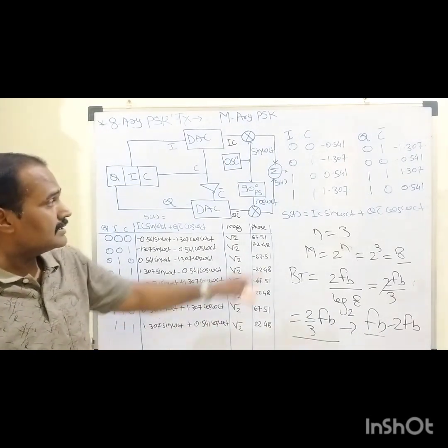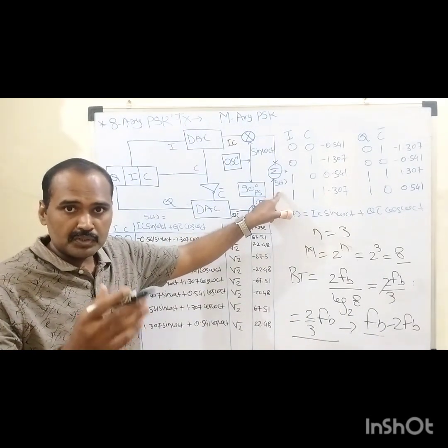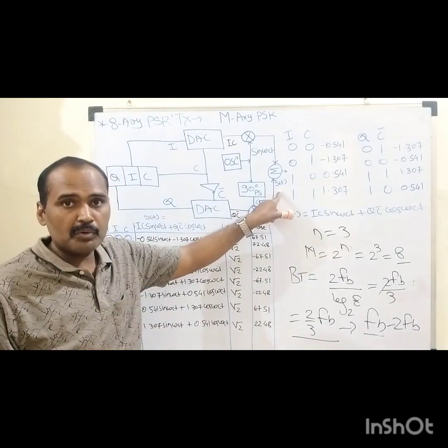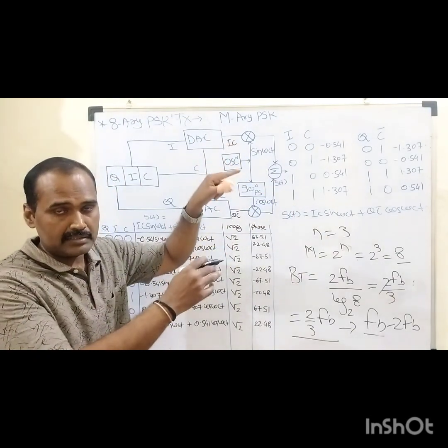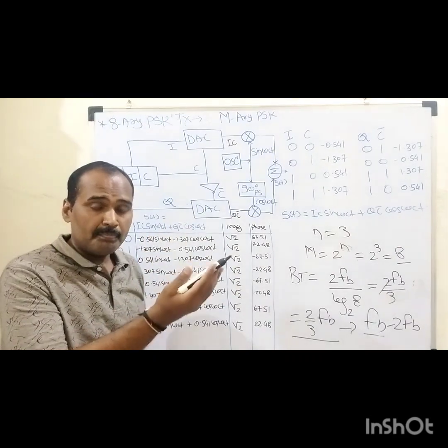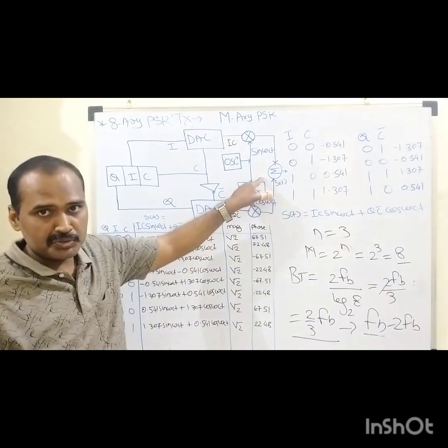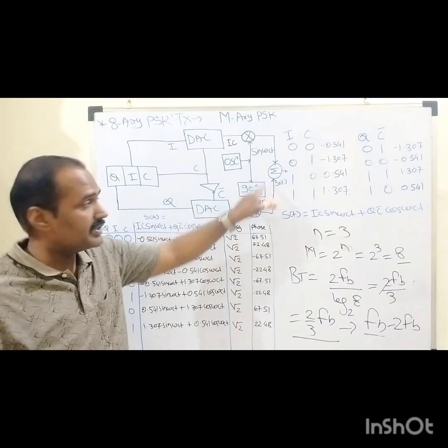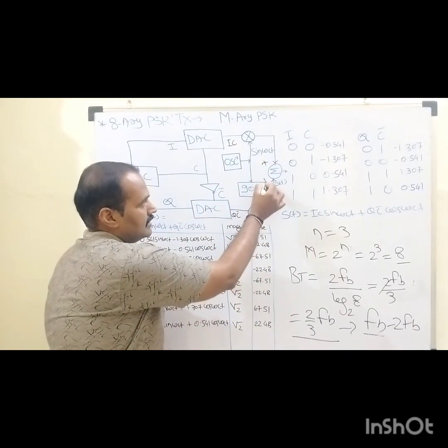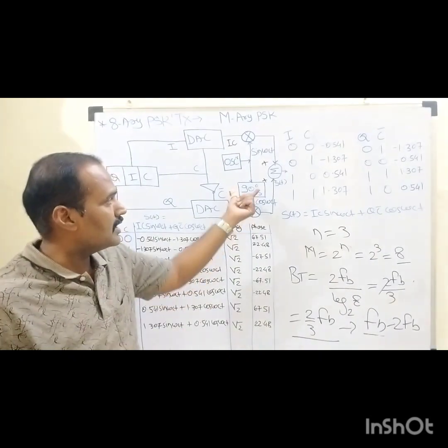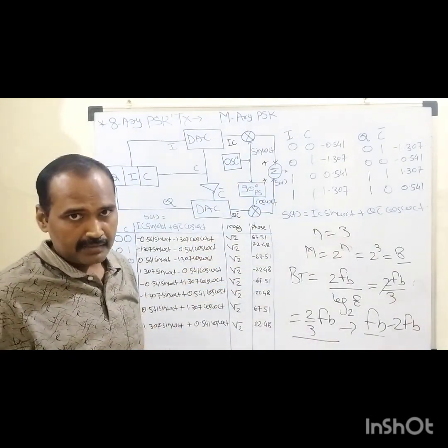So now the question arises, how to get this S of t? In order to generate the desired modulated symbol sequence, these two signals emitted by the upper modulator and the lower modulator are being added with each other with the help of this combiner or adder. As you can see, here also we have the plus, and into the lower terminal we have the plus sign.